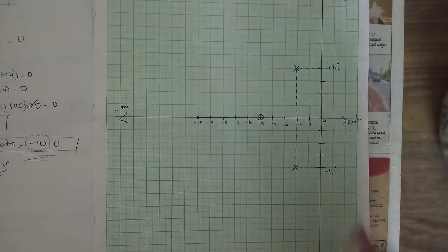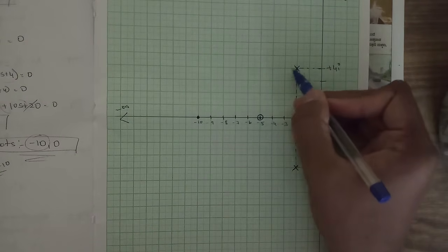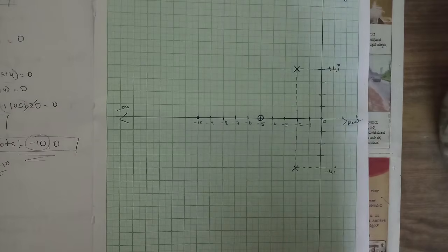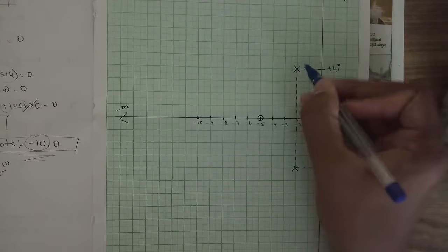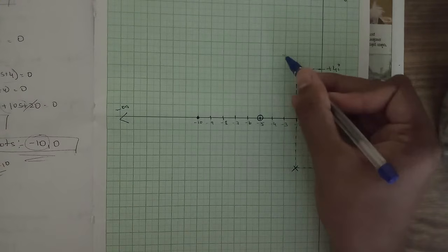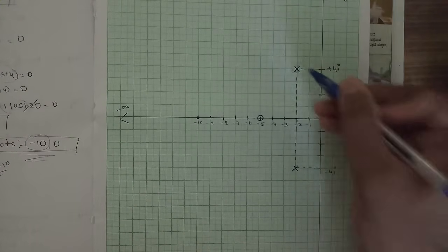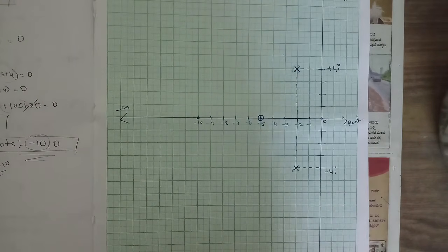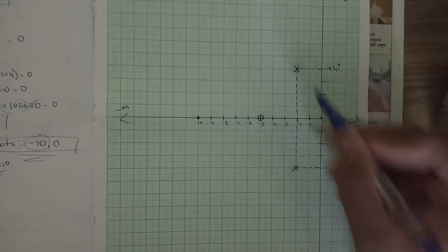That is, in which angle from this pole we need to be finding one angle, and from this pole we need to be finding one angle. If we find one angle with respect to this pole, whatever angle we get, its mirror image, the angle is here only. So in order to find the angle of departure, we need to be finding it for two different poles.